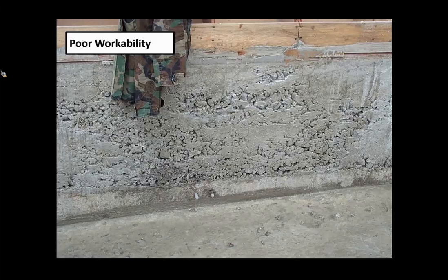The other thing associated to this project was the poor workability issue. As you can see here, this is an area of concrete where you have mortar in some areas and areas that have rock pockets, right? You can see that it's not really a well lubricated mix. There's an issue with not having the right lubrication.